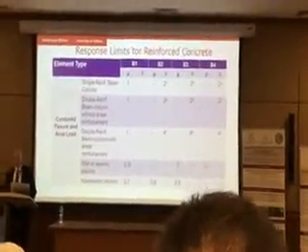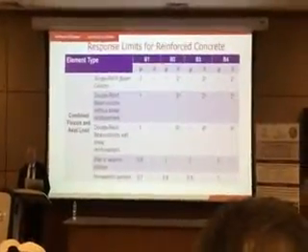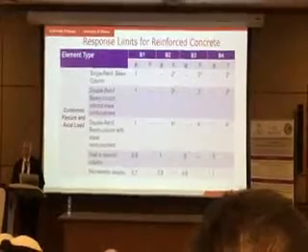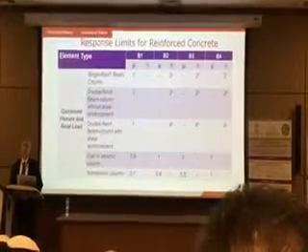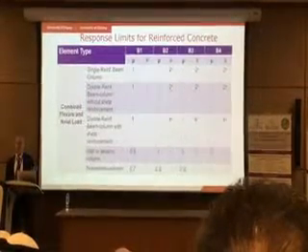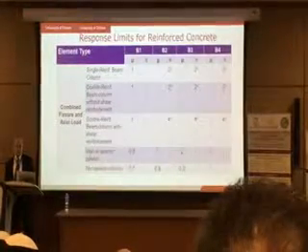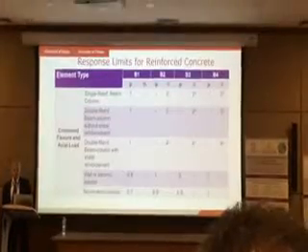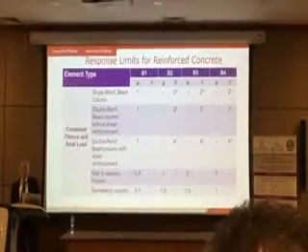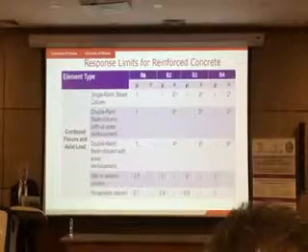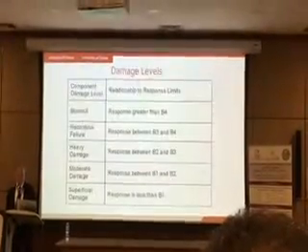This is for flexure and axial load, 2 degrees for vertical elements, columns, and walls. And these are the ductility ratios. Ductility of 1 means your member has to remain elastic because response quantity B1 is associated with operational performance level, for which you need very high protection.